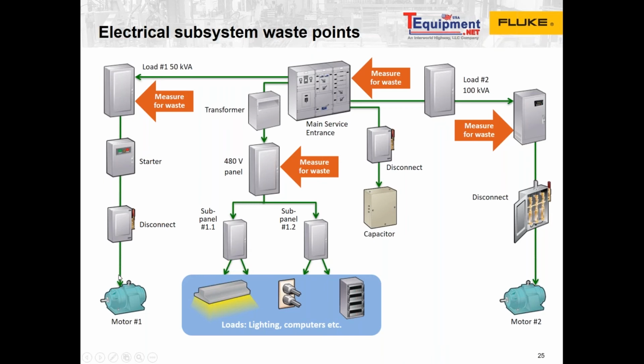With motors specifically, there is a Fluke power quality tool that does motor mechanical measurements. As in, you hook it up to the nearest circuit breaker or the drive that might be driving that motor, like the VFD, variable frequency drive, and it'll measure the torque. It'll measure the efficiency. It'll give you a lot of motor information, and it's live motor information while you're operating. So in that sense, you can tweak your operations, and by tweaking your operations, you could possibly get some kind of energy savings from that. So that's another way you can do it.